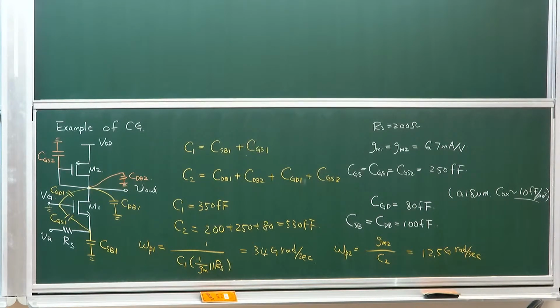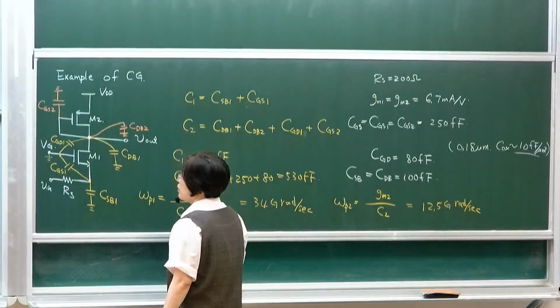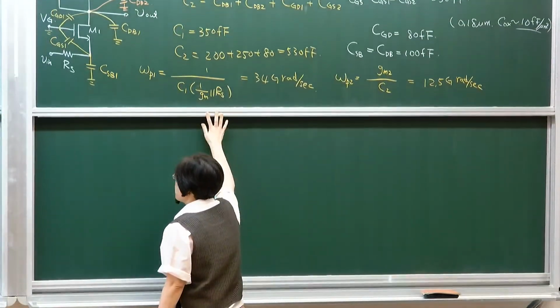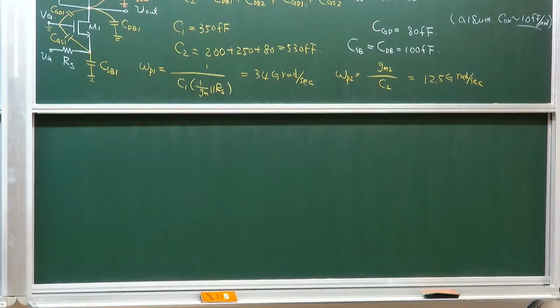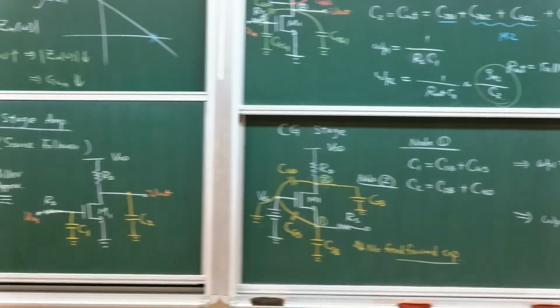So we're moving on to the last one, a single-stage amplifier, which is the follower circuit. So already you have the feature. I want to emphasize once again, for common source stage, you have Miller amplification. So typically your dominant pole is at the input because this has a much higher capacitance in most cases.